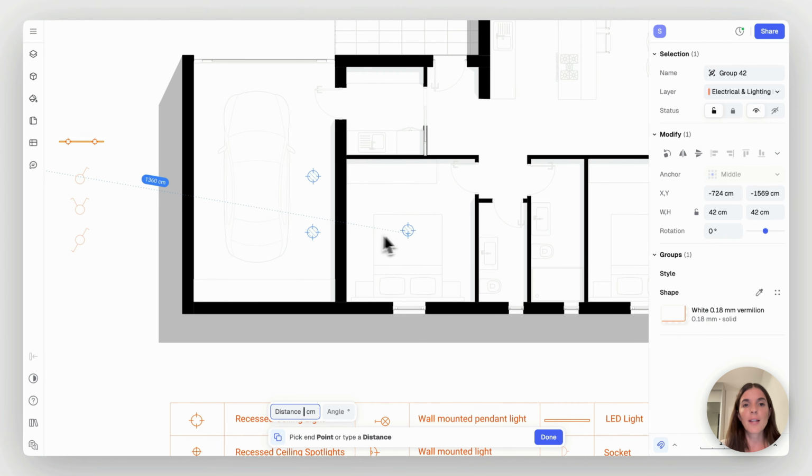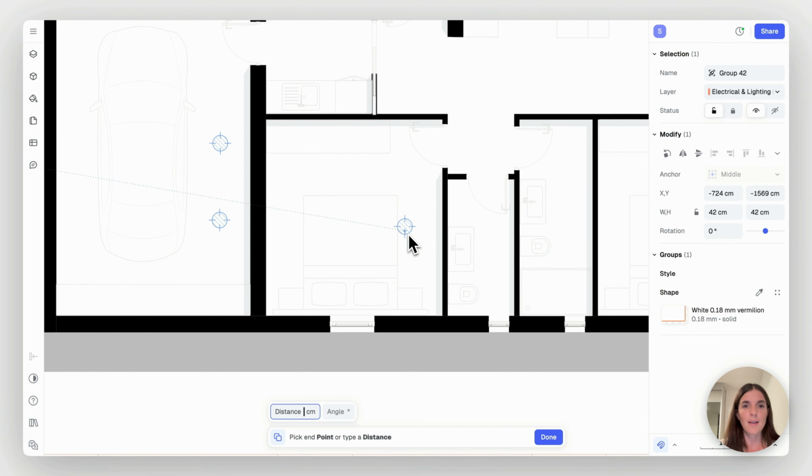The one thing that I will say as I start populating this floor plan is that there are different methods for lighting. And one of the things that is commonly done is just kind of placing a lighting fixture in the middle of the room. I normally tend to avoid that, thinking of the person within the room and what are they going to feel. So, for example, if I place a lighting fixture in the center of this room, it's above the bed, the person laying in the bed trying to read, for example, or do any other thing is kind of flashed by the light. So what I tend to do in these types of rooms is set them to the corner of the bedroom. Then this light also spreads into the closet.